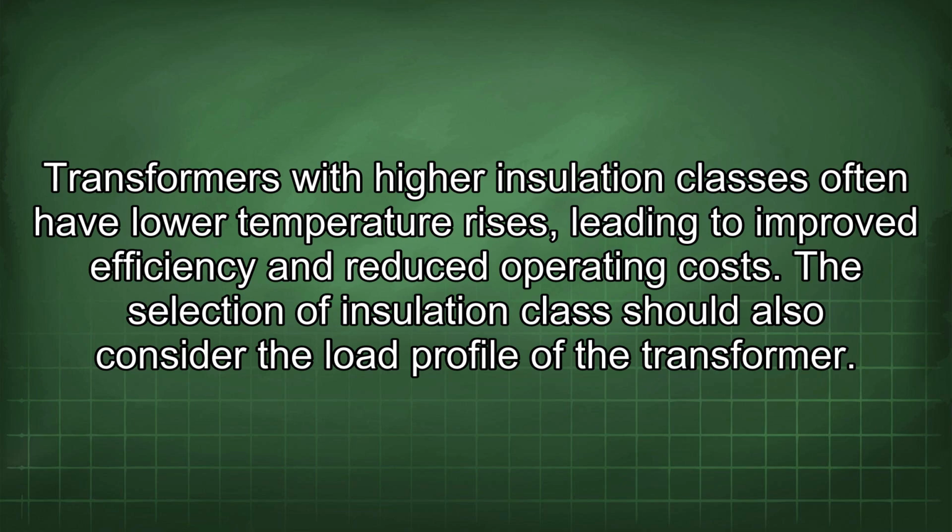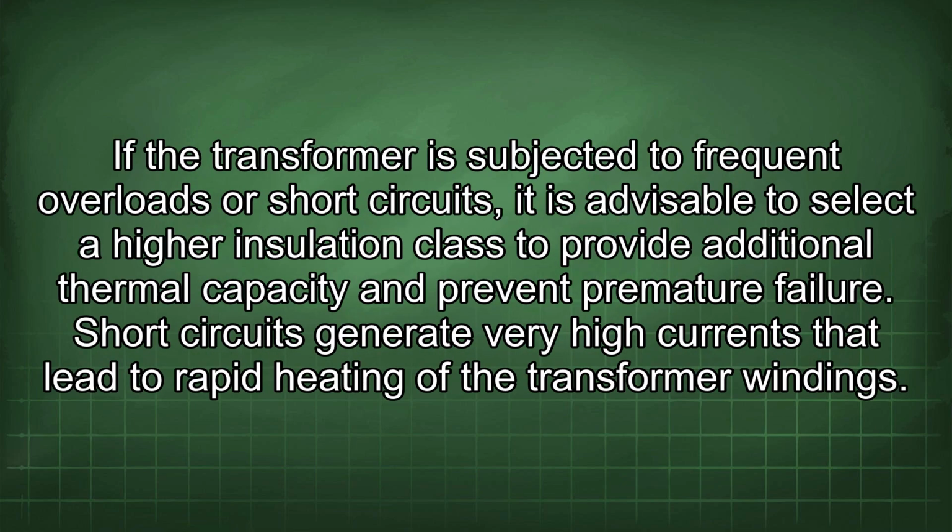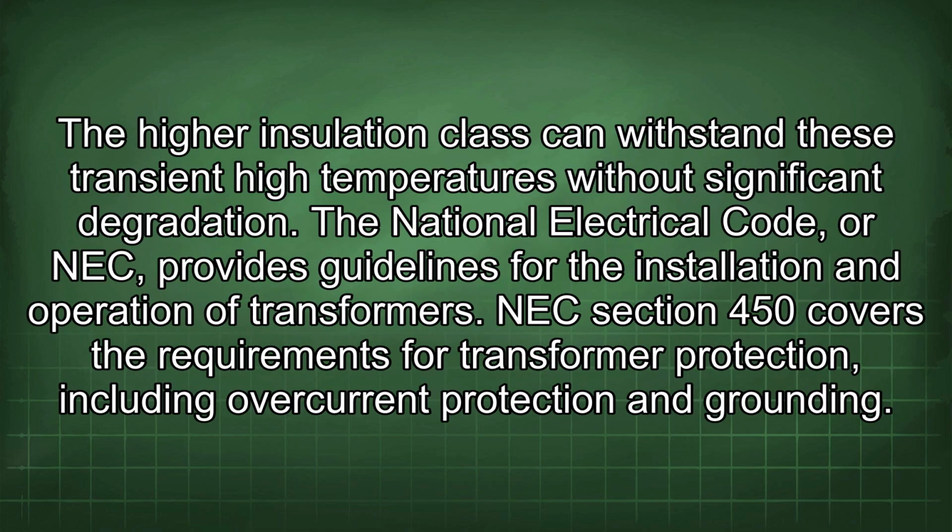The selection of insulation class should also consider the load profile of the transformer. If the transformer is subjected to frequent overloads or short circuits, it is advisable to select a higher insulation class to provide additional thermal capacity and prevent premature failure. Short circuits generate very high currents that lead to rapid heating of the transformer windings. The higher insulation class can withstand these transient high temperatures without significant degradation.